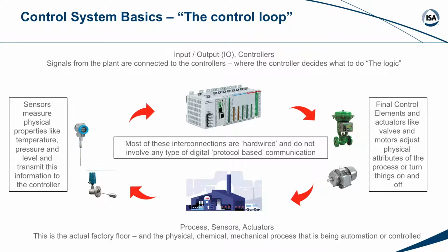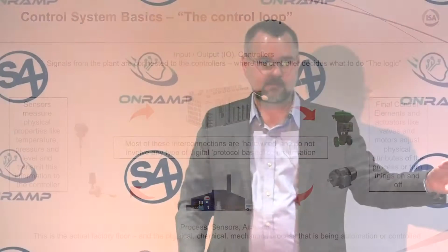And more of those final control elements and the sensors out in the field are becoming intelligent. Remember, at one time, not that long ago, when I started, that was pneumatic, that was air pressure, right? The sensor was changing air pressure. Then it got to electronic, where it was changing the voltage or current. Now it's sometimes sending a digital signal across some type of bus architecture. And a lot of times in an older facility, you'll have all of those operating at the same time in different areas of a plant. So lots of diversity, I guess, if you wanted to use that term.